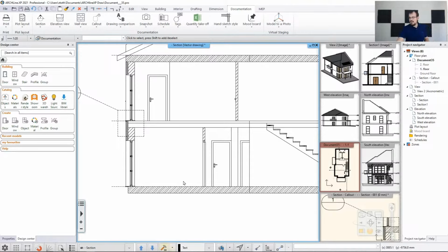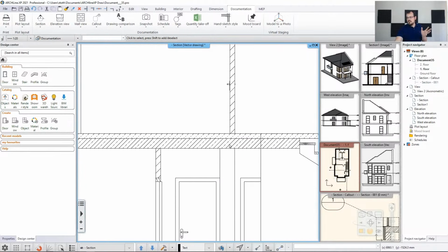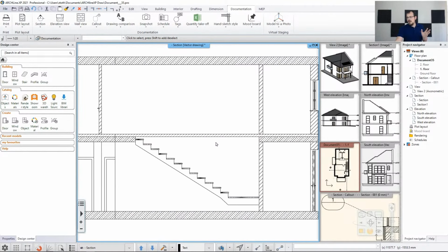You just click on the 3D hammer and then the section updates, and you see both layers with the correct hatch patterns, with some issue over here. If you add an additional layer to a slab, the additional layer has no idea that it has to inherit the cutout, the recess over the staircase. So you have to amend that manually. You might have to do that. So how do we do that?